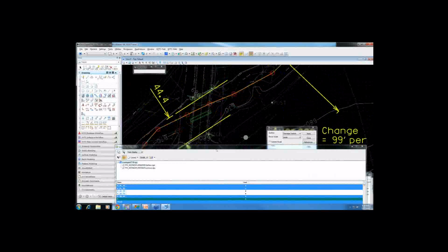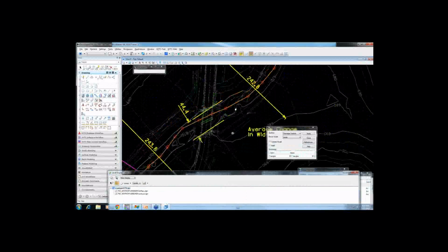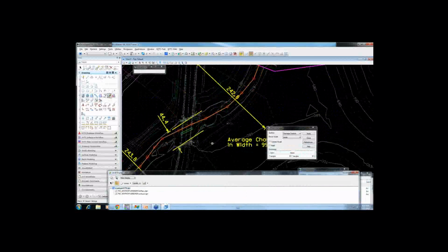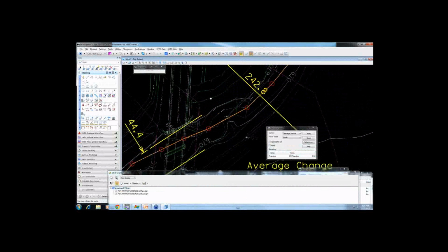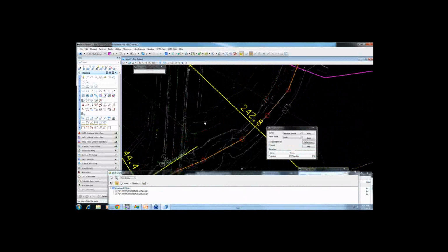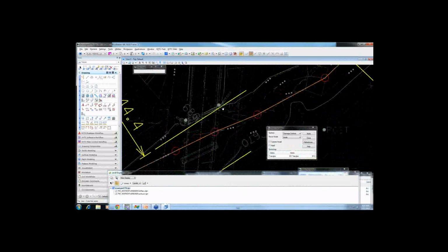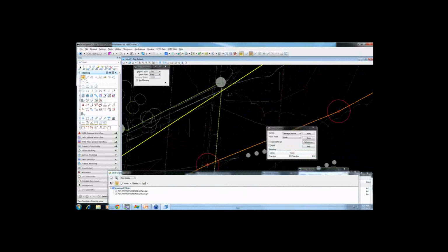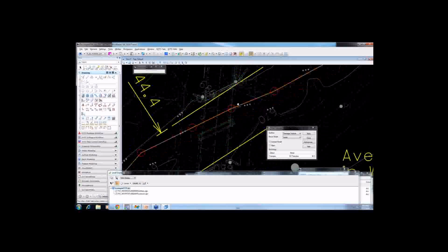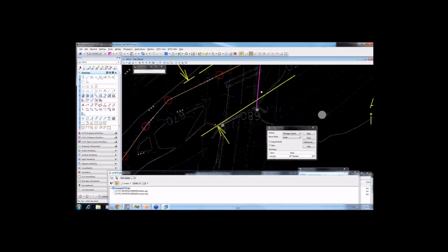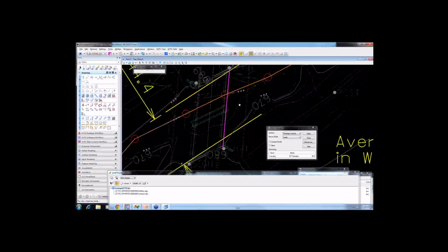So I dashed them so that when we drew over them, you'd be able to tell what I was doing. So I'm going to get this line style up. Okay, so the first thing I do when I'm doing this would be to get them parallel to the bridge, and the easiest way for me to do that is just to trace that edge of bridge feature.